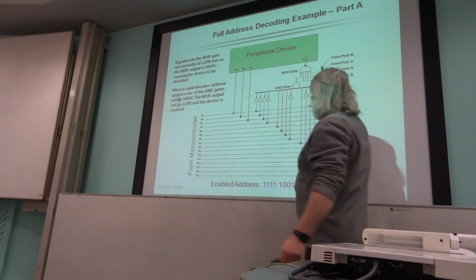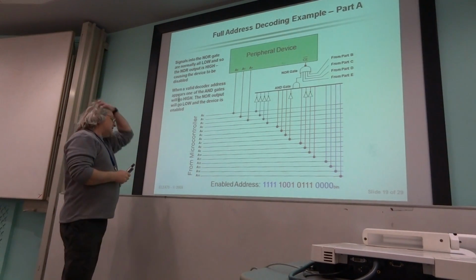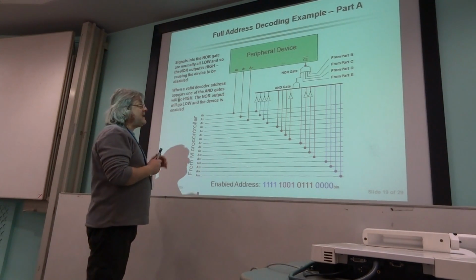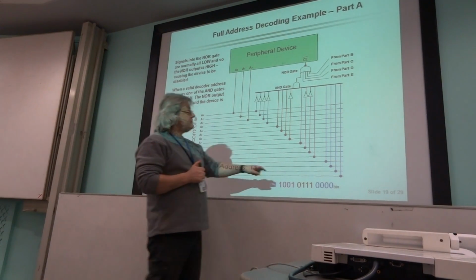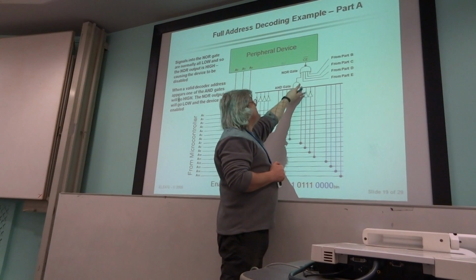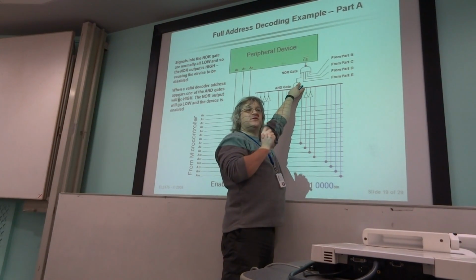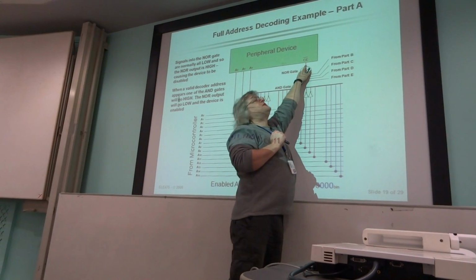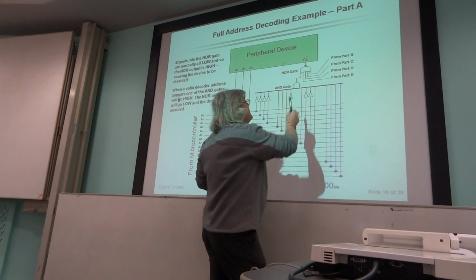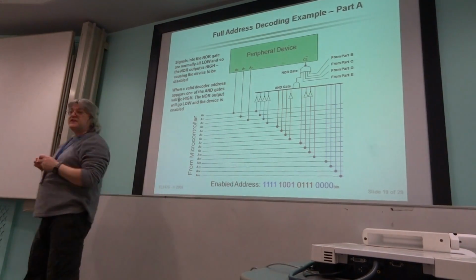Okay? And this chip enable goes low when the device is awake. So what we're doing here is effectively we're feeding, we're bringing all this in. Now there's 5 different addresses where this has got to go low. This particular slide is only a 1/5 of the address decoding logic.